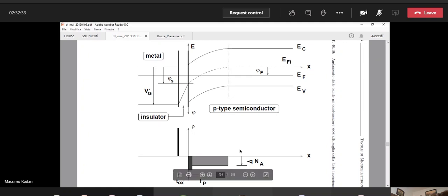We express the charge of the semiconductor as the superposition of the charge due to the dopants plus the charge of the layer of electrons, if that layer exists, so if you are in the strong inversion condition. If the layer does not exist, we simply put it to 0. So we try to set up a general theory that is simpler than that used so far.